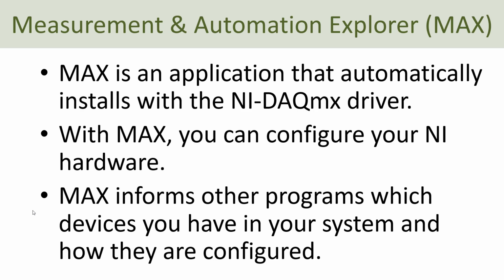Next, I will introduce a software called Measurement and Automation Explorer, shortened MAX. MAX is an application that is automatically installed when you install the NI-DAQmx driver software. With this MAX software, you can configure your NI hardware. Typically you can change the name of the device, and you can test it to make sure that the device is working properly before you use it, in this case in Visual Studio and in C#.